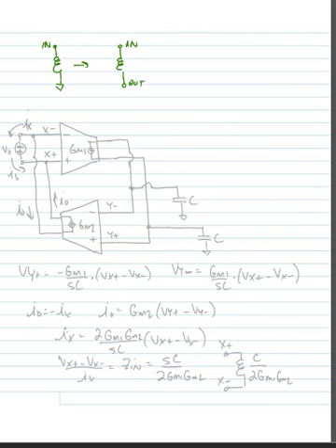So for instance, we could make a transconductor that was fully differential, and that might look as follows. So here we have a GM1, and we have some kind of current source inside this that represents our transconductance. This is dependent upon the voltage at the input, and it would be a differential voltage at the input. We use another transconductor to feed back a signal to the input.